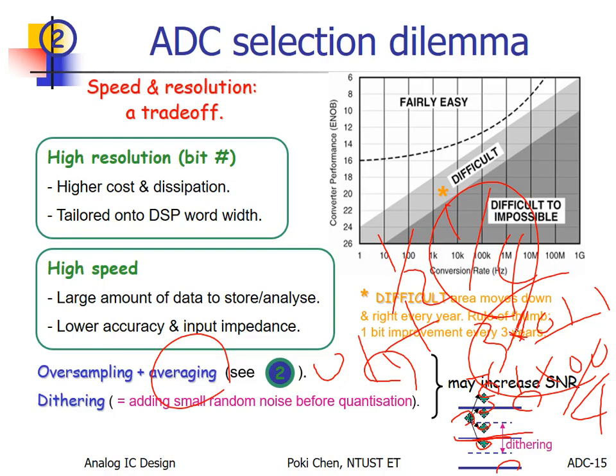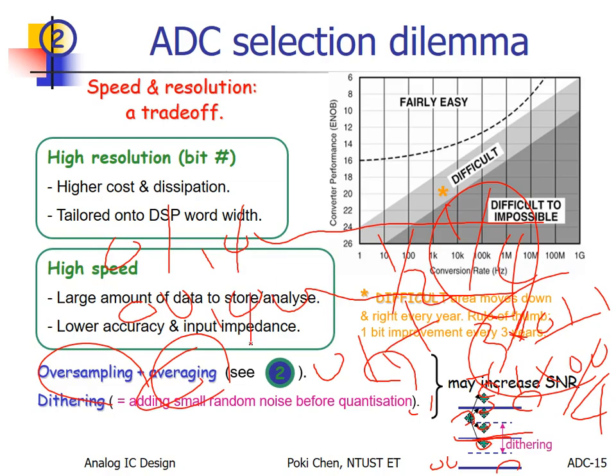You will get something after the point, because 0, 0 means I have only 0, 0 here, 0, 1 there from the beginning. So it means 0.000 all the way to infinity. But after oversampling and averaging, you will get something beyond the point. Oversampling and averaging can enhance your accuracy. Sometimes we call it dithering.